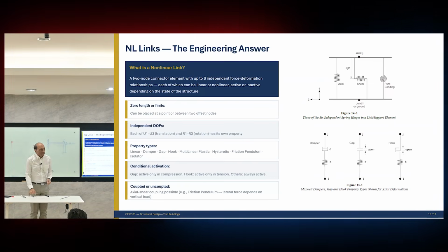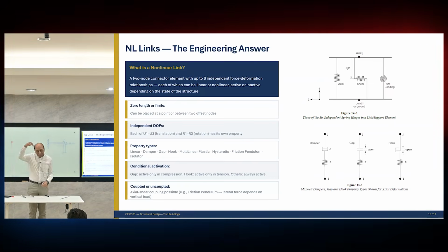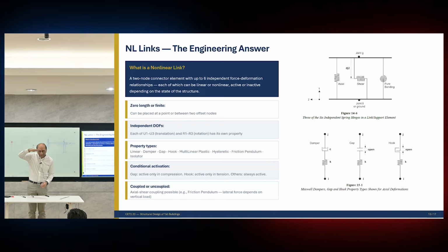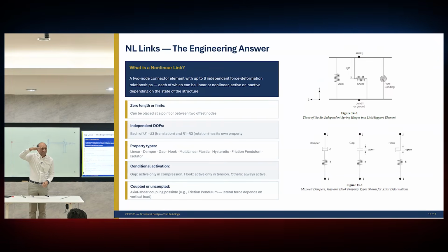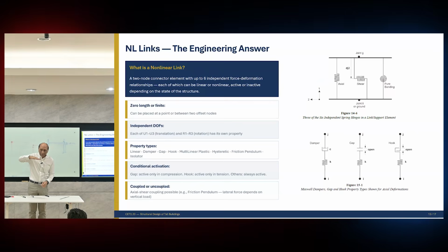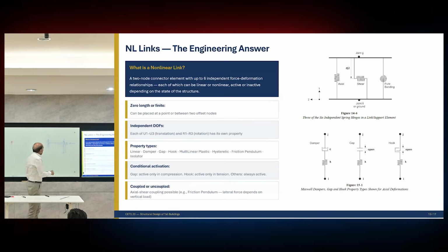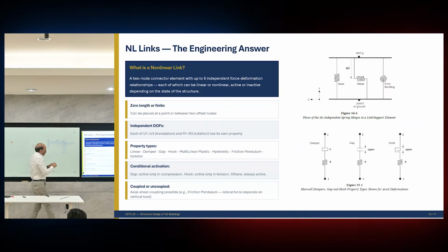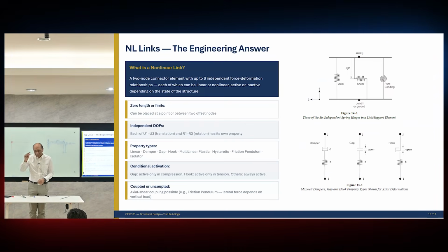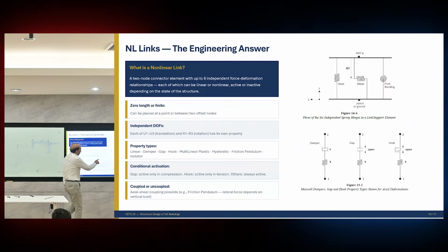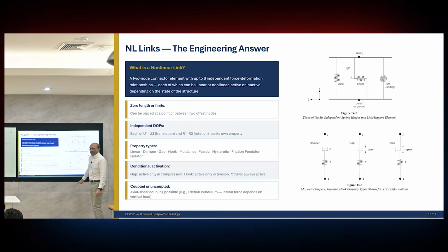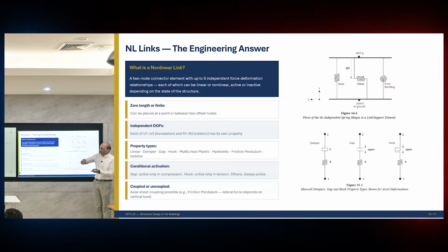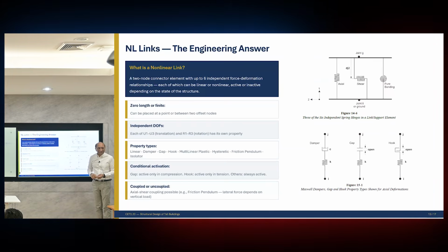If you apply that load P, the cantilever will deflect freely in a linear elastic manner. Let's say the load is also here, W. When the cantilever deflects by 10 millimeter, then this gap will be closed. And after that, the load will be transferred by the stiffness of that wall underneath.